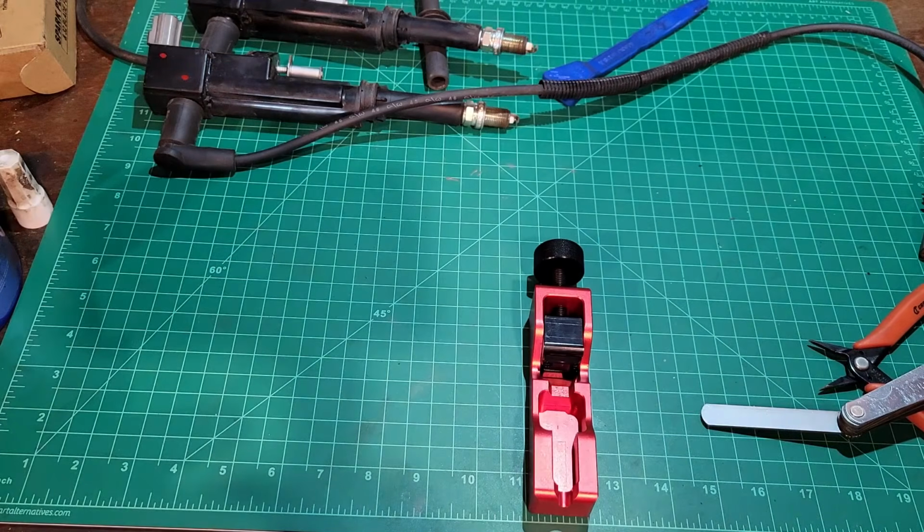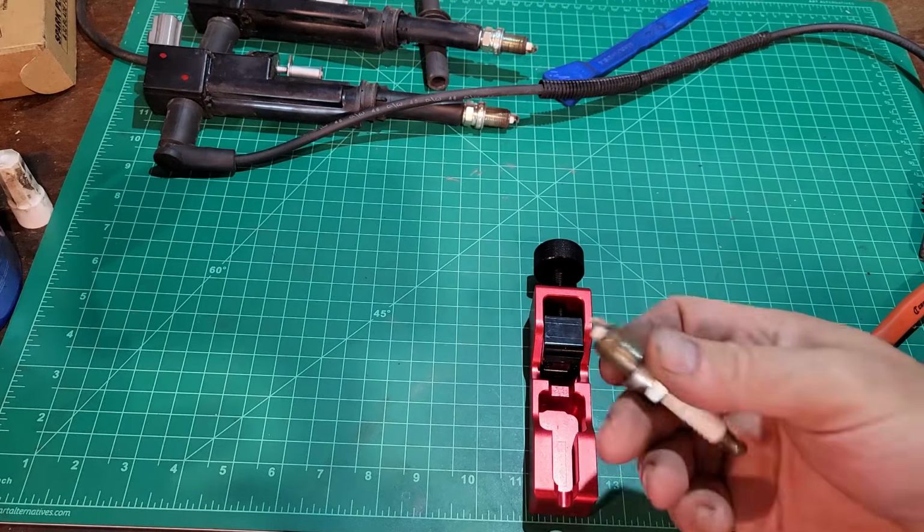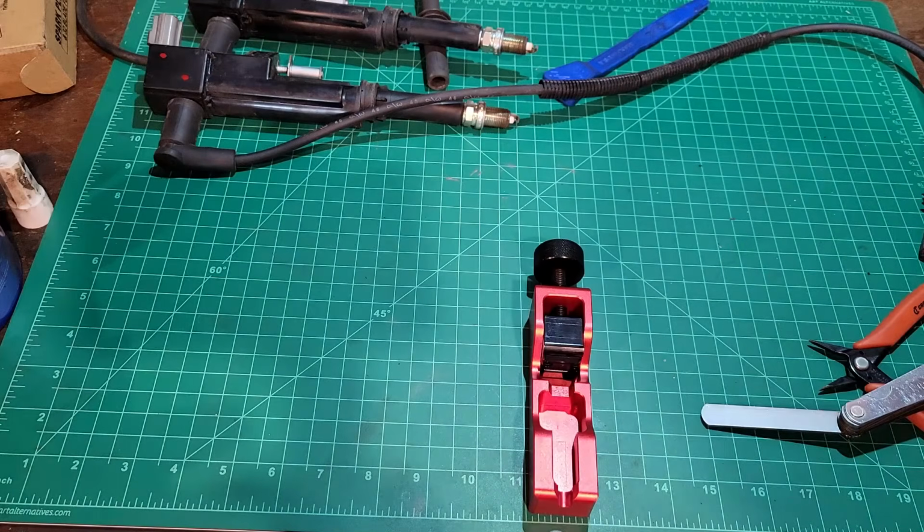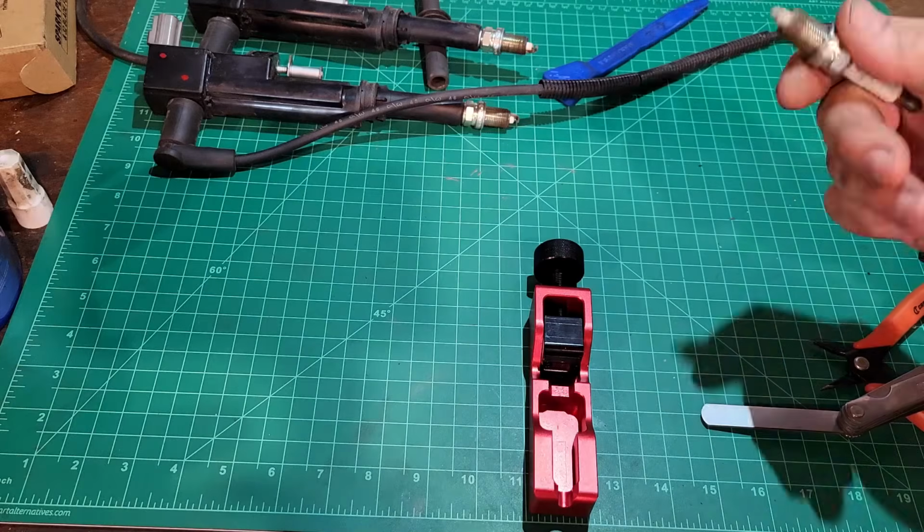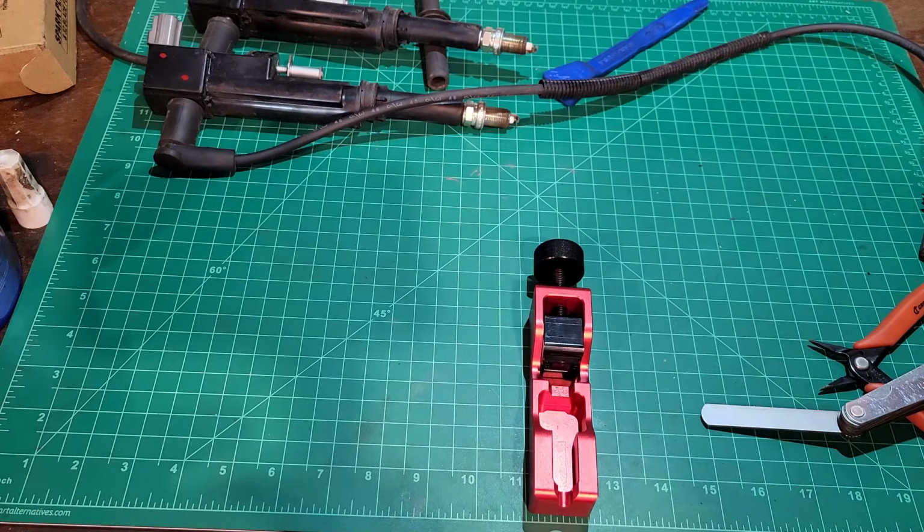Anything that you don't know anything about, you've got to start somewhere. It's trying to take fuel away. You know, is big spark plug gaps going to cause that? I don't know. Two of the plugs were almost hand tight. Will that cause that? I don't know, but at least we're going to get it back to baseline. And I couldn't find a vacuum leak without smoke.